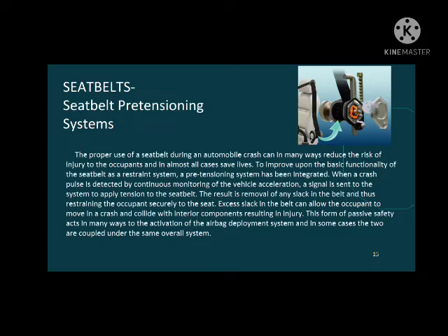The pre-tensioner consists of an inertial wheel combined with a pendulum which moves to lock the belt into place during sudden deceleration. Most drivers have experienced the frustration of pulling a seat belt from its reel only to have it lock unexpectedly, or of driving down the road and feeling the seat belt gradually getting tighter and tighter. This is the action of the mechanical pre-tensioner at work.